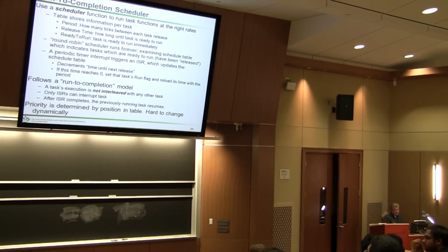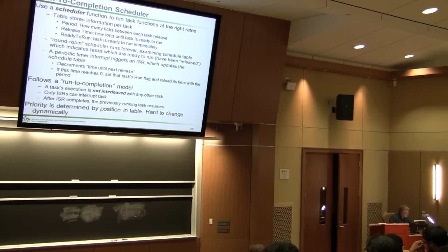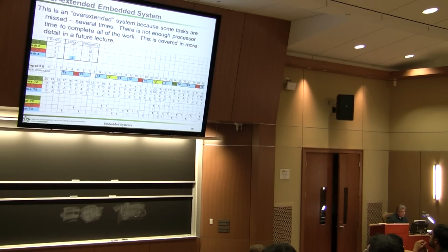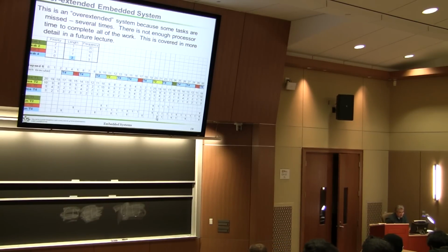And that's important to note, that it must run to completion. So in the example that I showed here, or I'll even make it show this example up here. So in this example, let me find a good one, right here. Notice that task 2 is running, and it takes 2 timer ticks to run. But at this time, number 21, it determined that it's time for task 4 to run. Task 4 is a higher priority over everything else.